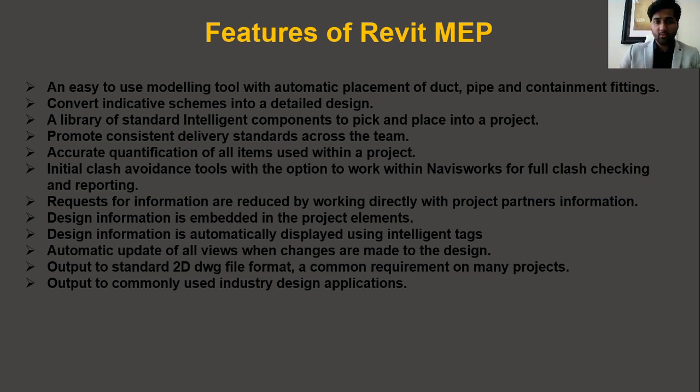We discussed this already, like we can convert or export the Revit file into various other industry design applications. Let's talk about software from a different provider, for example Tekla or Bentley, which has a different file format, right? It won't have a DWG format or .rbt file format, which is the default format of Revit. It has a different file format of its own. So in case you want to convert into those file formats, we have the standard file format, which is the IFC, which you have already seen, so that you can easily export your Revit file into those software.